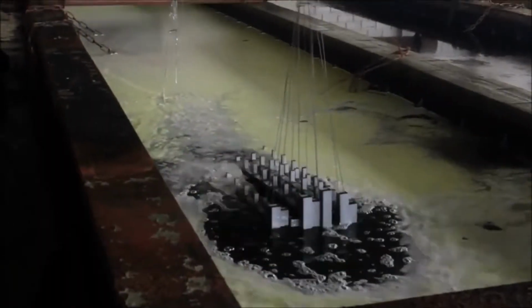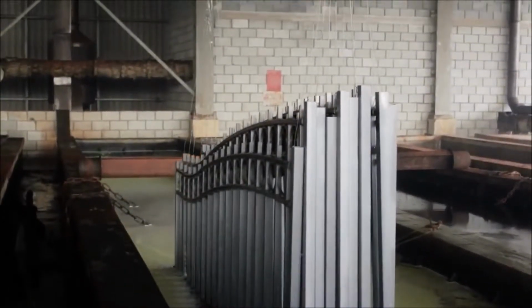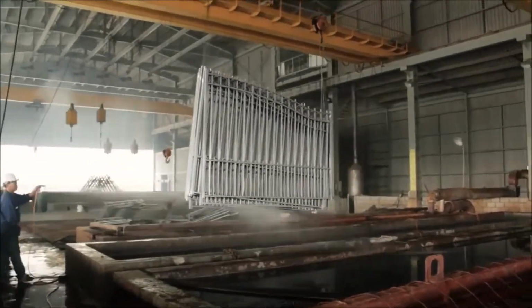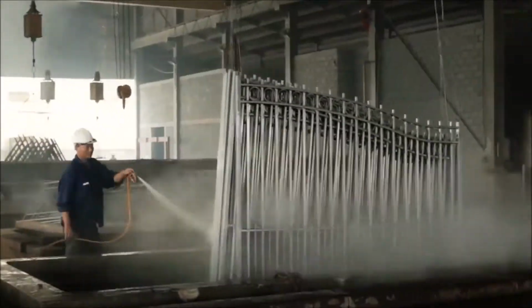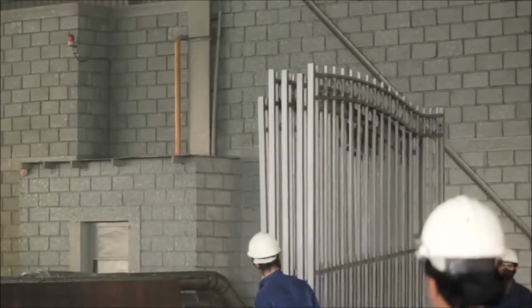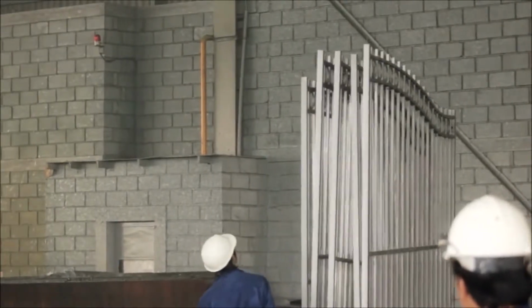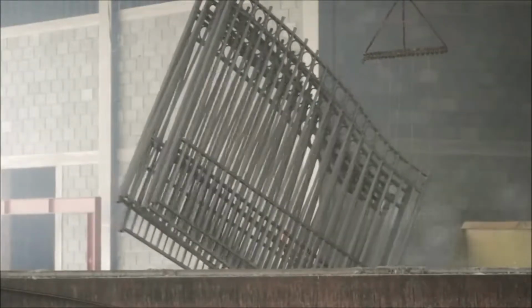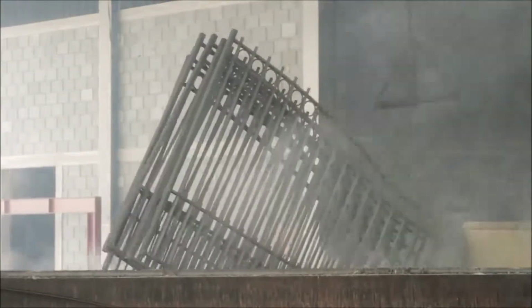So here we are at the hot dip galvanising facility, where the gate and fences are dropped off, and prior to being dropped into the molten zinc, they need to go through a three-stage chemical treatment process. The first stage is a degreaser, and then it goes into an acid wash, and then into a flux. From the flux, the product's taken off of the hanging jigs and put onto another hanging jig that enables it to be dropped into the molten zinc where it's not touching each other. Once it's been assembled on the hanging jigs, then it gets dropped into the molten zinc.